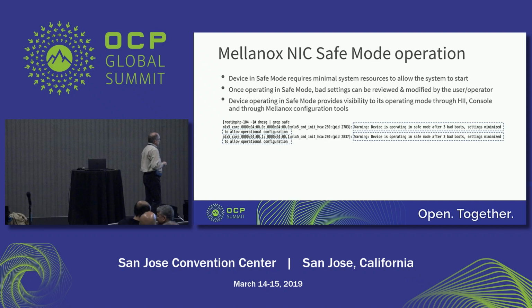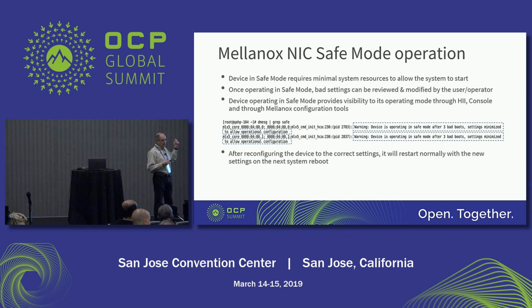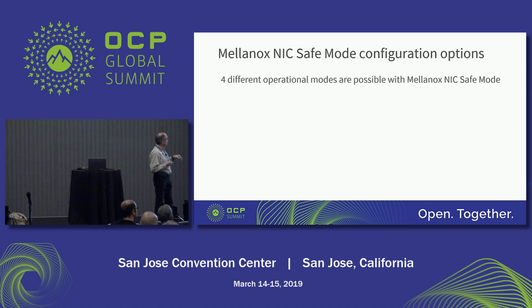So this is a capture that shows you that a given device is already operating in safe mode. You know that it has happened, okay? If you open your HII menus, you'll see that marked in the corners, as you would expect. If you query that from the BMC, again, you'll have clear indication that you're operating in safe mode. The only thing that you need to do now is just to rectify the settings, the bad ones that caused the whole thing to happen, and that's it. Reboot the system, and you wake up fully functional. You don't have to take the card out of the system.